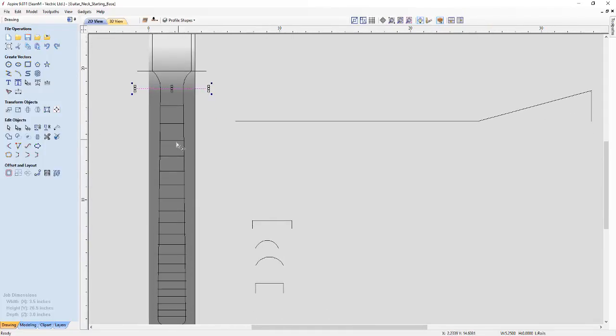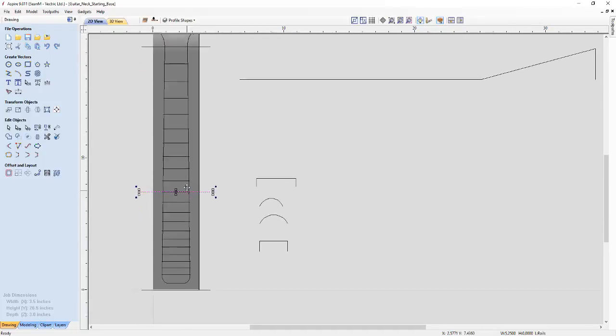Then we want to create one at the 10th fret, so we know where to start our 9/10 high profile shape. So I'm again going to get the center, hold control, and count down as we snap into each one of the fret positions. That's 1, 2, 3, 4, 5, 6, 7, 8, 9, and 10, and just let go of the mouse there.